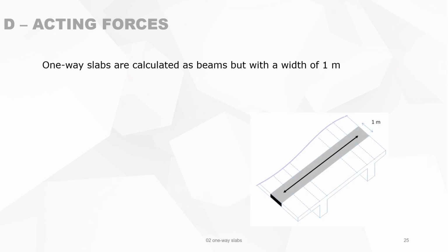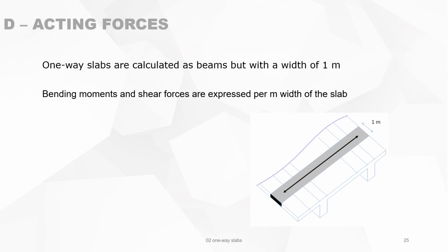I have made a little sketch. Look at this slab supported by two beams. You take 1 meter width and you calculate this as a beam.